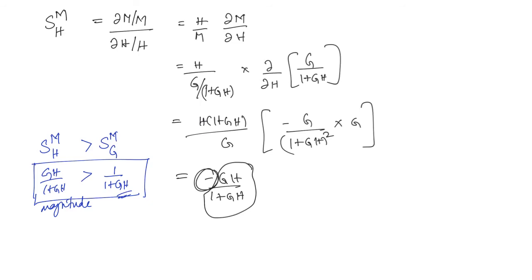This sensitivity with respect to the feedback path transfer function will only exist for a closed loop system, because for an open loop system we just have the forward path transfer function and no feedback path. So we need not compare with the open loop system.